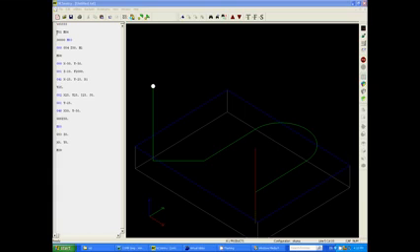Okay, so currently at the moment we've got tool 1 in the spindle and we're doing 6,000 RPM with the spindle running in a clockwise direction. Now when you put the block of material in your vise or clamp it down or whatever, you're going to have to set a datum point, which is what I just showed you before, using the machine's software or whatever to set up an offset position, which is known as a job offset. Now along with that, when you set up your tool, the tool needs its tool offset set up as well in a tool file.